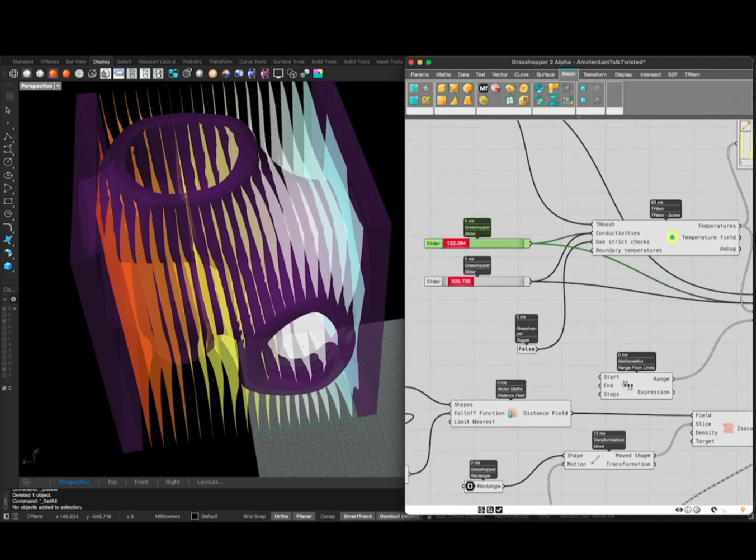Yeah, to conclude this, I do want to make one practical point clear, and this is the materials. So you somehow have your mesh, you have a tetrahedral mesh, and each single tetrahedron needs to be in one material, either in the infill or in the gravel or in the concrete, and it needs to be associated with one thermal conductivity value. How is this done in a way such that you don't get too much headaches about doing this?